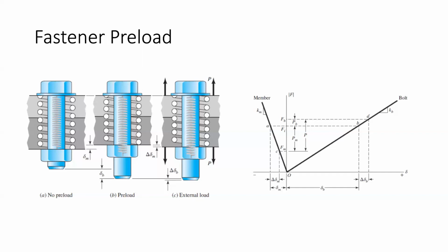And essentially, it's mostly use of this calculator, but you choose different combinations of these thread sizes depending on what kind of constraints you have in the mounting pattern of your system. And once you choose that thread size, you can go and check, is this proof load actually large enough? If not, then I have to upsize my fastener or redesign to have more fasteners to generate the correct amount of proof load in the system. And from there, the calculator tells you how much proof load you can generate before either of the threads fail. And once you have the proof load, you can back calculate, based on these friction values, the actual amount of torque that you need to turn the fastener.